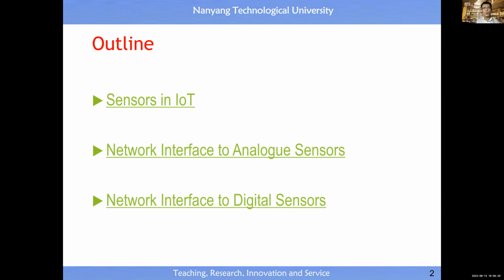And we also know that the microcontroller by default could be considered as a built-in sensor for voltage, because the microcontroller allows you to convert analog voltage into a digital number, right? So this is why we spent lecture 2 studying the way of interfacing analog sensors.